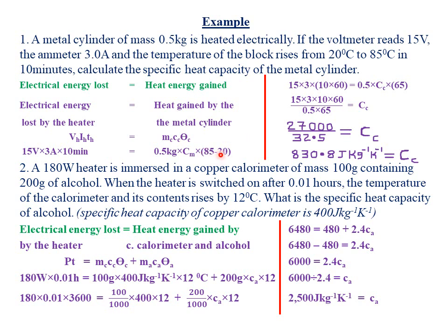Remember, we said when we find the change in temperature, we are not concerned with the sign. Therefore, you simply take the larger temperature minus the smaller temperature so that you get a positive value of temperature change. Then you also saw that the temperature change in degrees Celsius is just the same as the temperature change in Kelvin, which are the SI units. Therefore, the temperature change will simply be the final temperature 85 minus the initial temperature.